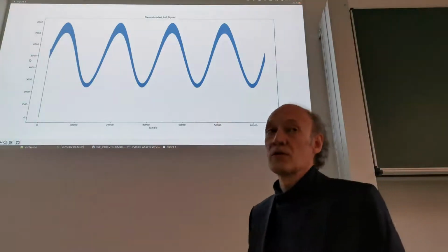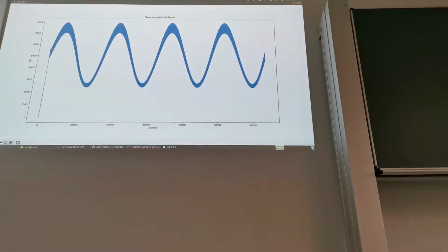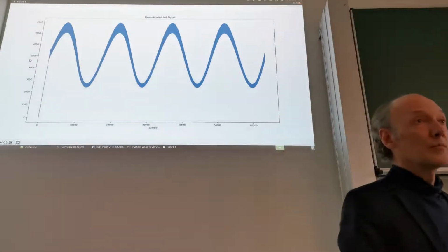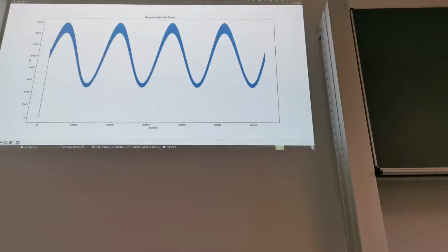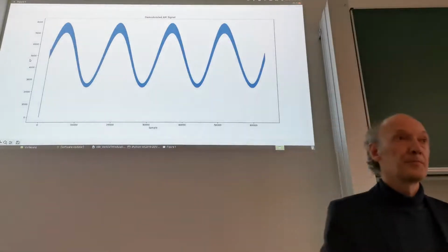In this case, this unknown factor comes from using an unnormalized FFT, so it depends on the length of our FFT. But that's the problem in general with amplitude modulation: we will have a factor A which is not really known. So we have to normalize it, and that's usually done using automatic gain control in the receiver. The receiver always normalizes the signal to a certain desired output.